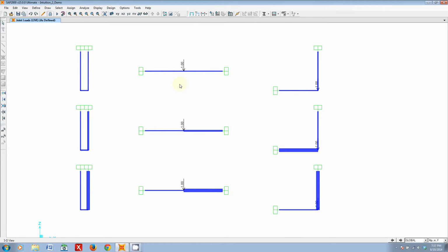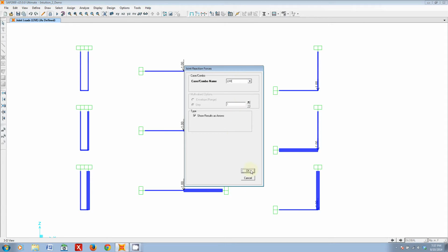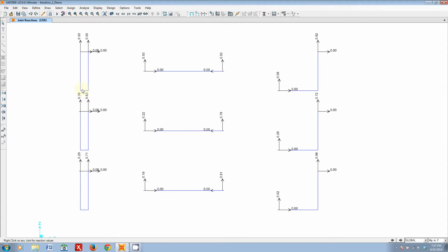Through the beams, because remember how I said that the load can go through two different paths. It can go pretty much to the left one or to the right one. It can go through the beam or go through the rod. And we can see if it's a unit load, then, in this case, these two cases, it's getting split 50-50 because the beams and the rods are equal.